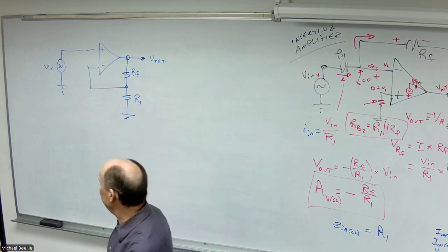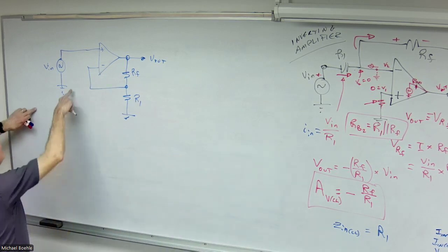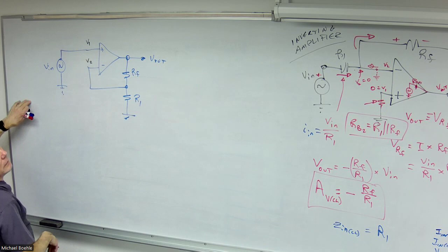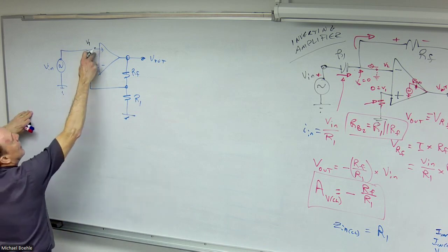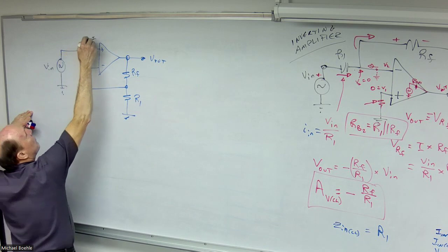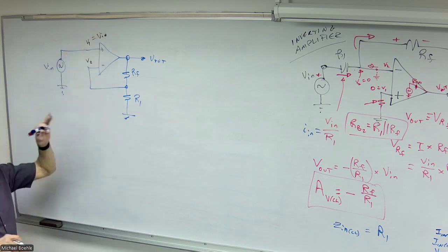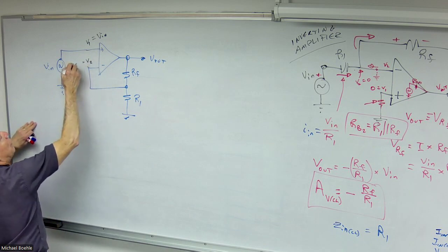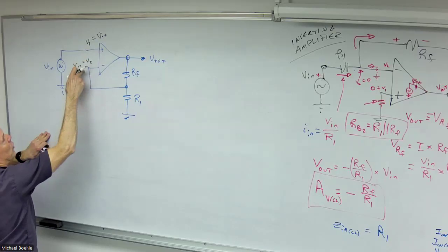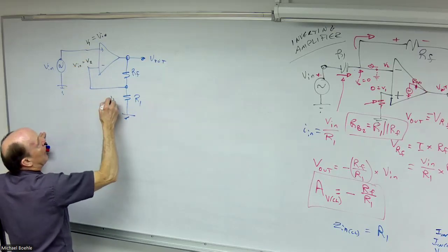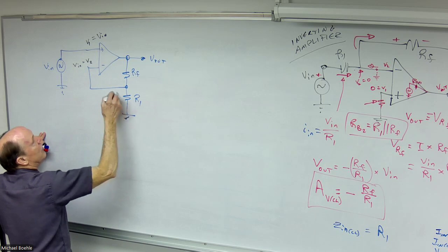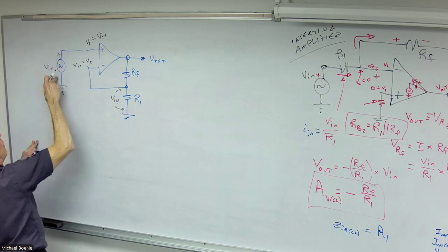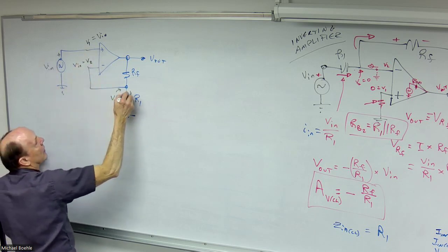So same assumptions here. Now, here, V2 is not grounded like I had over there. Or no, V1 is grounded. Never mind. Okay. V1 here is the input voltage, which because of negative feedback means that V2 is also equal to the input voltage. Well, V2 is connected across R1. So the input voltage is across R1. I'm using the same reference points, right? Plus, plus, plus.